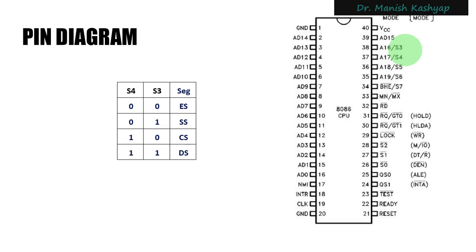And remember that apart from these segments, there is a lot of memory which is vacant, which is definitely used for interrupts. Like in 8085, we saw that there were vectored interrupts and their locations started from 0000 and 0008, like that there were some specified address locations at which you used to keep your programs.